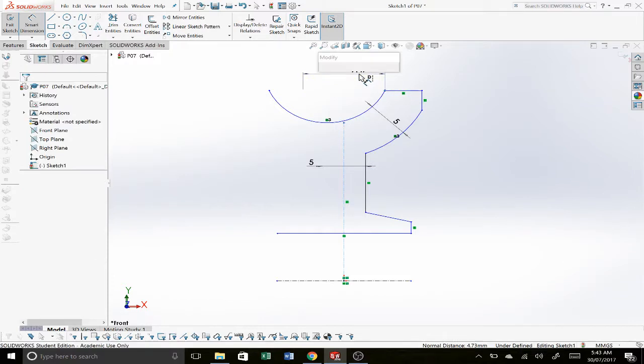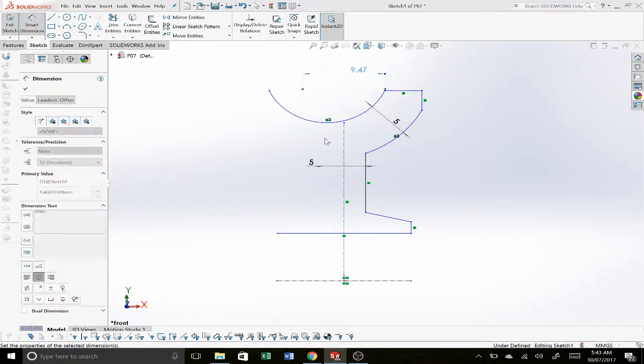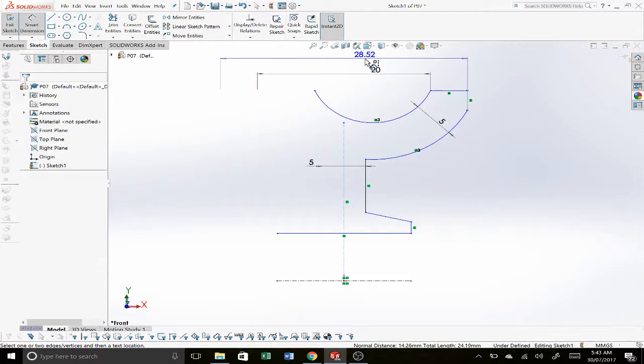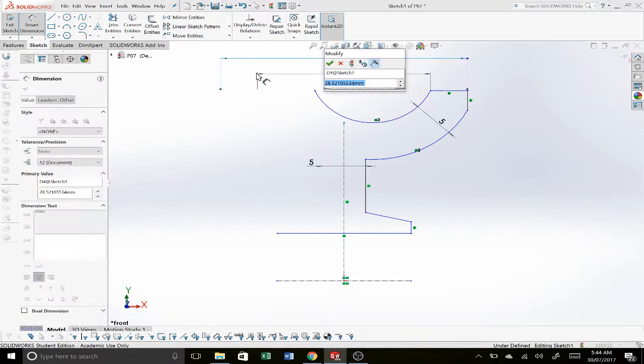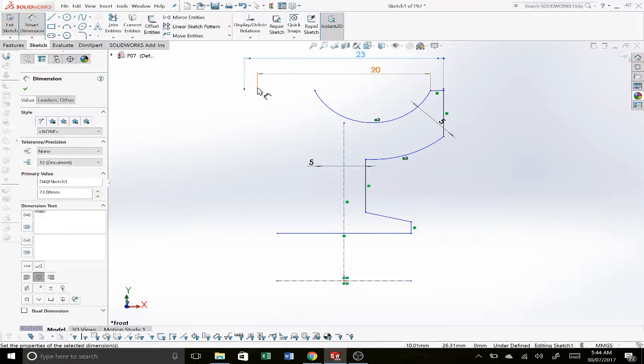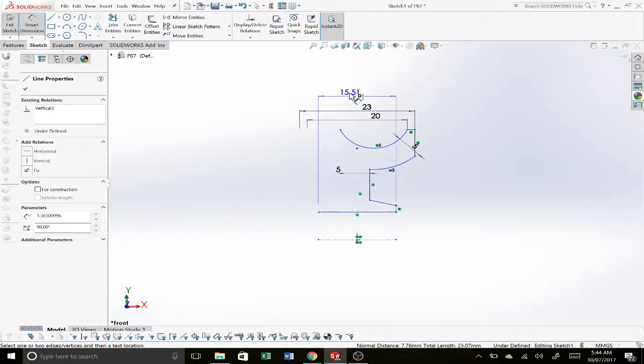So let's chuck that down. So I'm using the center line here. You'll notice the center line is selected, and that's what's allowing us to dimension to those imaginary points over the opposite side of our screen there. These 2 points here are what I'm talking about. There's nothing there. It's just guessing that we want it to be across that center line.